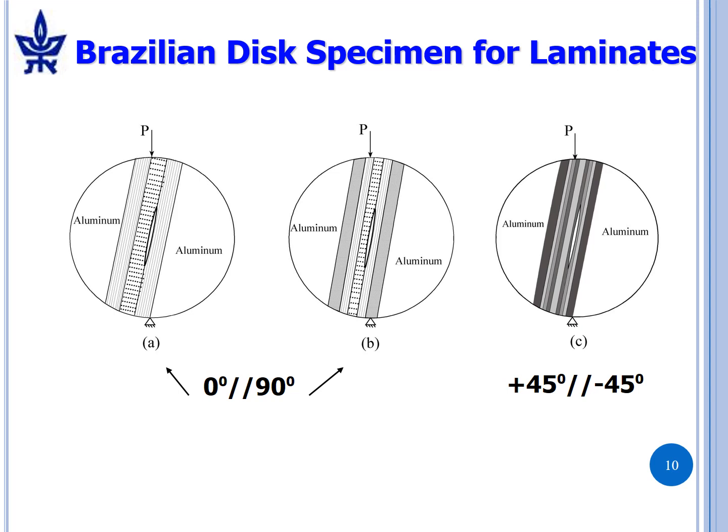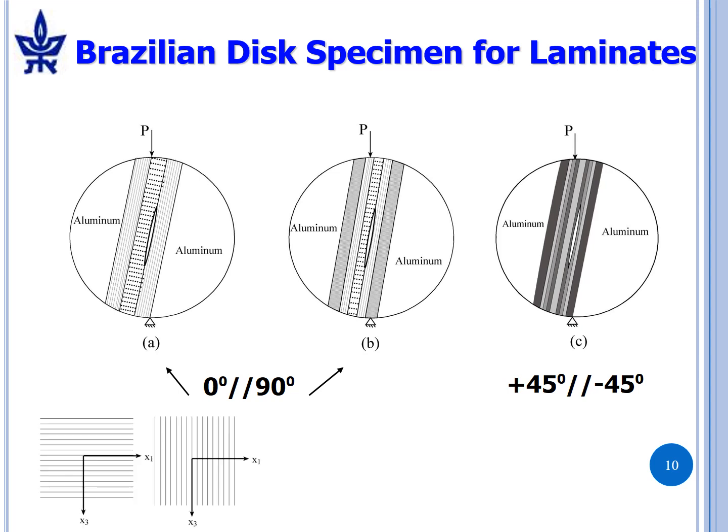There's a number of plies which are coming out at us. The fibers are coming out at us in the 90 degree direction, and we can look between an X1, X3 plane. We have X1 along the delamination, and we have X3 coming out at us. And we have two different layups. Here, the strip is about 4.5 millimeters. So we have 4.5 millimeters, 4.5 millimeters, and 4.5 millimeters.